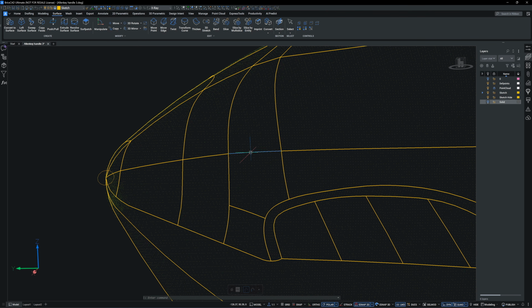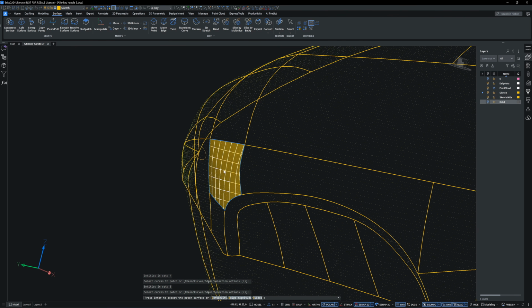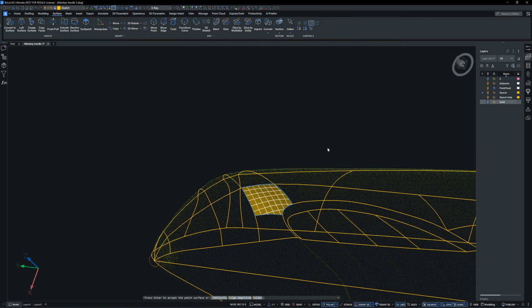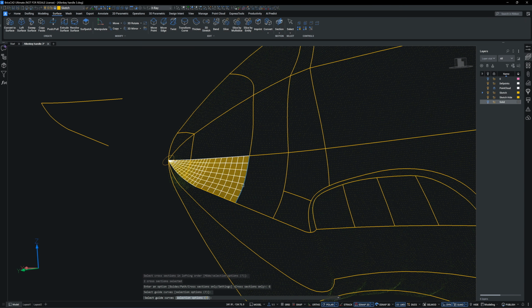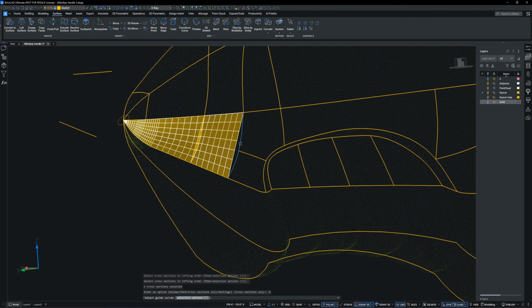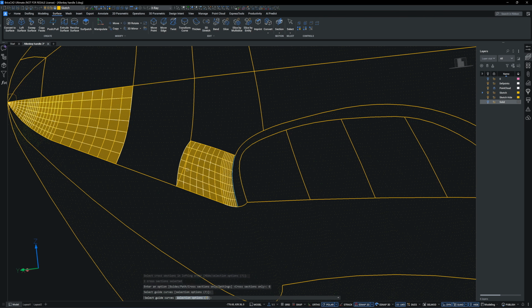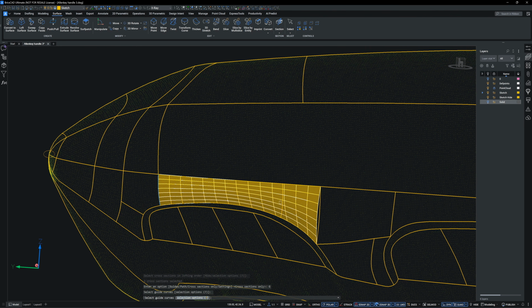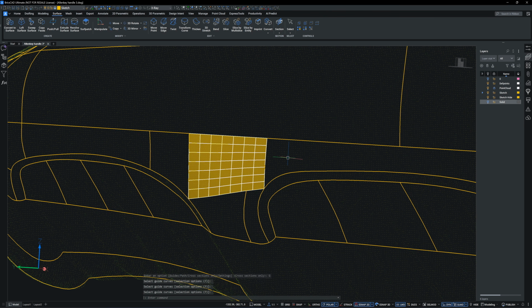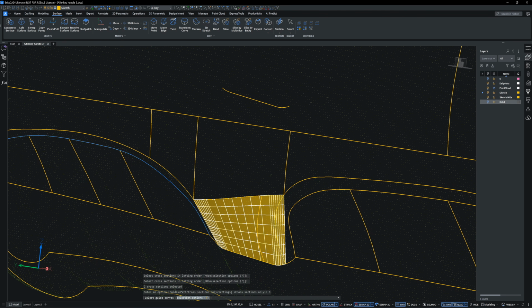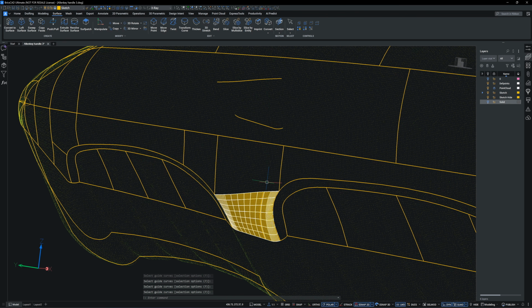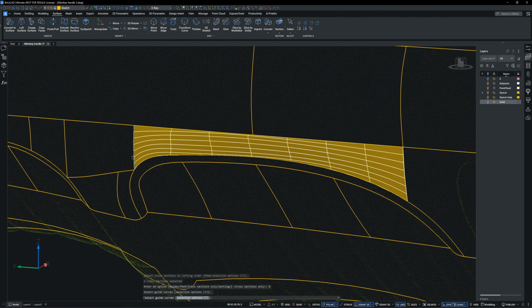When the boundary has more than 4 sides, you can try using the surface patch. It works well in this particular area. I often take jobs from sculptor artists who create only half of their model. It's faster to rebuild the geometry in CAD and then mirror the other half for them, ready for 3D printing.